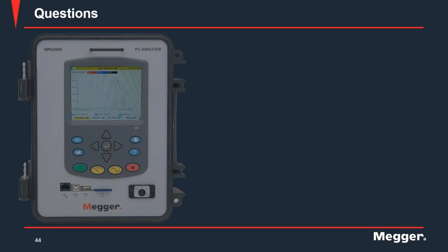Now, on the con side, since they do operate off DC, that means they have to have an AC to DC rectifier in them. So they do create harmonics. Now, we're talking very low current here, so it's very minimal harmonics, but if you're replacing an entire facility with them, it is recommended to do a harmonic analysis before and after, to see what impact it may have on other systems. And the other thing to keep in mind, if you're going to LEDs, is that you will need special dimmers with them. So if you're going to be using dimmers, they have to be specially designed for that LED that you're using, so it operates properly with the power supply that drives the LED.